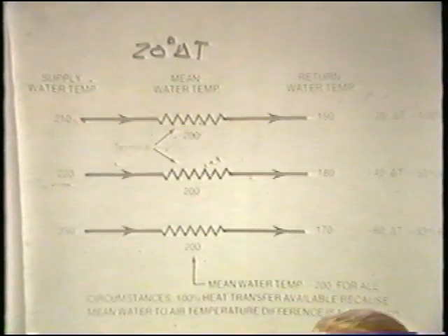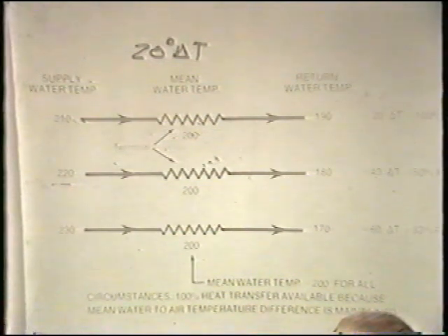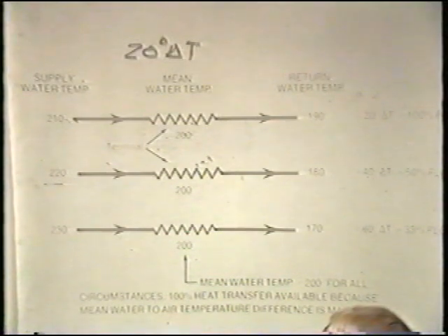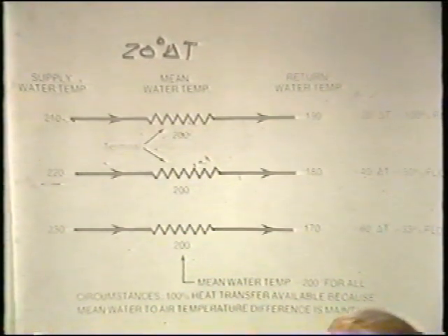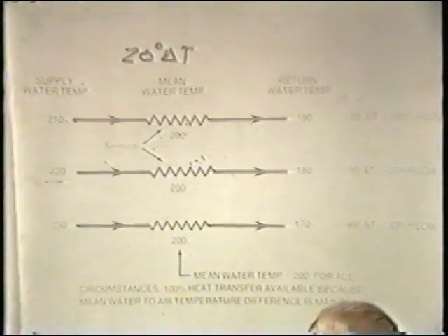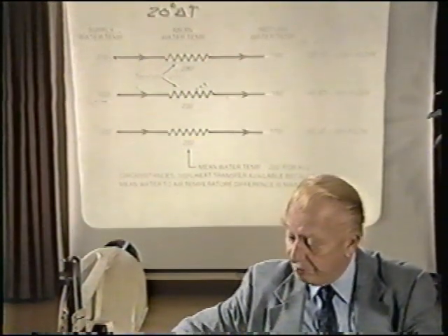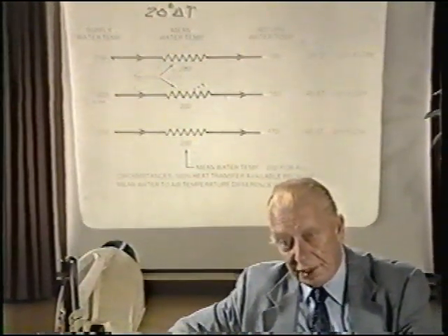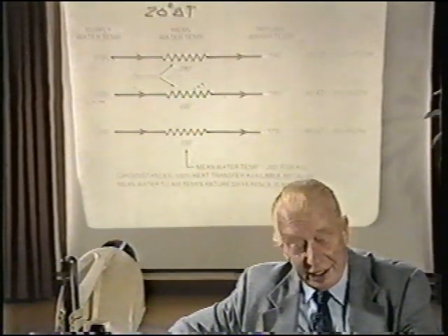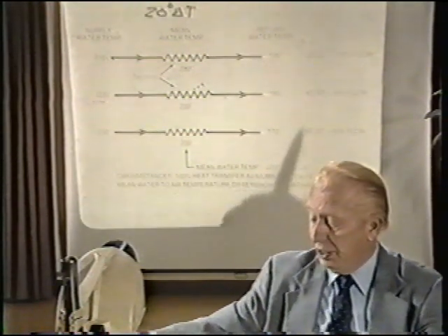The use of a 20-degree temperature drop as a design tool for baseboard systems, hot water systems, has to do with the fact that at a 20-degree temperature drop, 1 gallon per minute flow rate equates to 10,000 BTU per hour conveyed in the piping system. It has no true relationship to overall system design, except that it's a very convenient approach in terms of design.